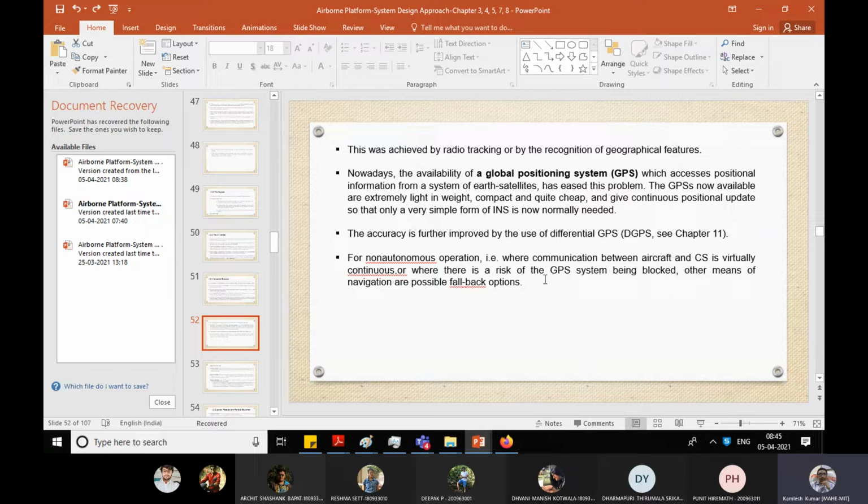So let's see how DGPS works. Mostly one receiver will be installed at a known location. Let's say in Manipal, correct? You locate one receiver in Manipal, and your aircraft is flying maybe near Mangalore, correct? Mostly within 100 kilometers there is no error; very little error will be added. So you should go more than 100 kilometers. Now Mangalore is 65 to 70 kilometers. Let's consider that it is crossing the error, the error which is recommended for DGPS.